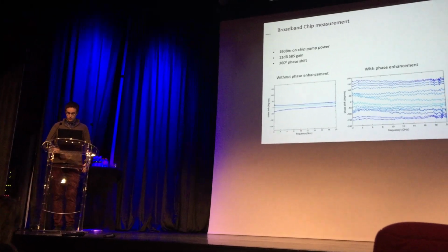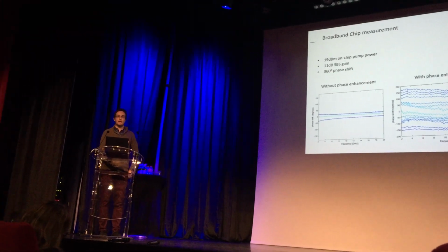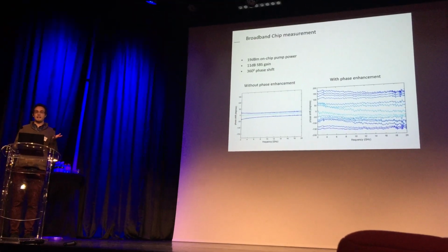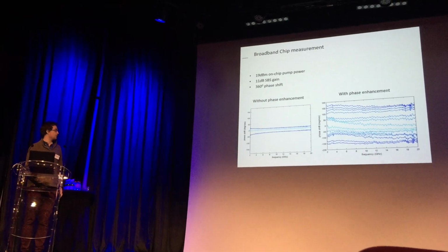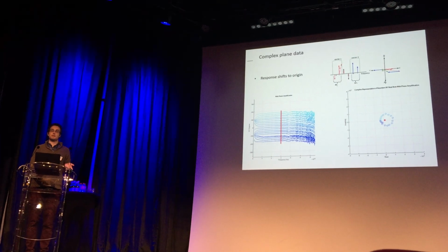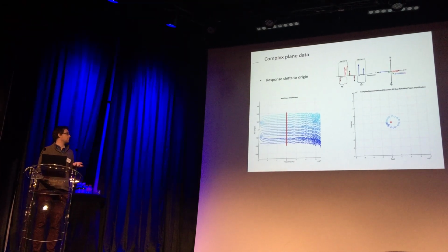Yeah, we do. So when we were doing the single laser setup here, shown on the left, we were just using a regular bandpass filter, and it had very low insertion loss, and as a result, the link gain was much higher. But when we wanted to do the dual bandpass filter, we needed to use a wave shaper, which has much larger insertion loss. So that's one potential location where that could come from.